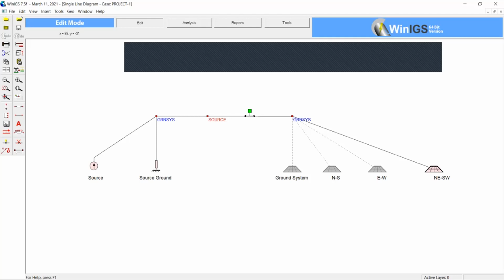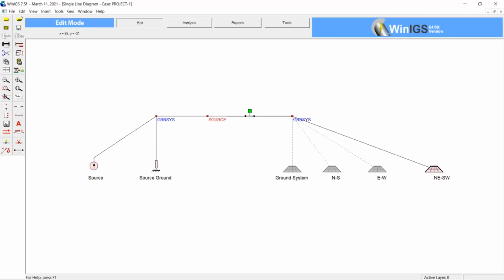Oh, wonderful. Okay, now what we have to do is mix up those 3 different soil models. How will we do that? Each model has its own top layer resistivity, bottom layer resistivity, and height. So you will take the average value of top layer soil resistivity, bottom layer soil resistivity, and the height.